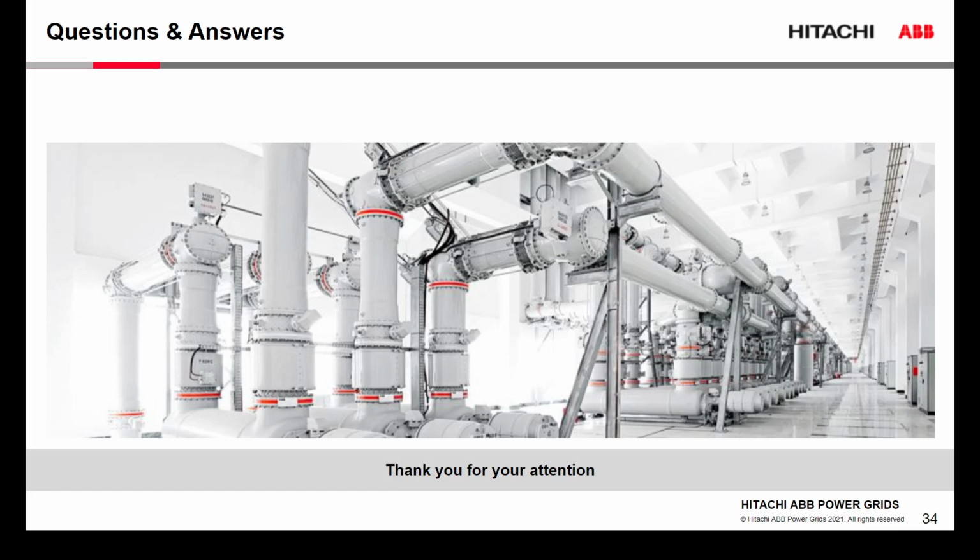would need additional support, like heating blankets or heaters for the circuit breakers. With the GIS having more modules, that is something you try to avoid, and you would usually go indoor at such temperatures. Another aspect is being close to a very corrosive environment.